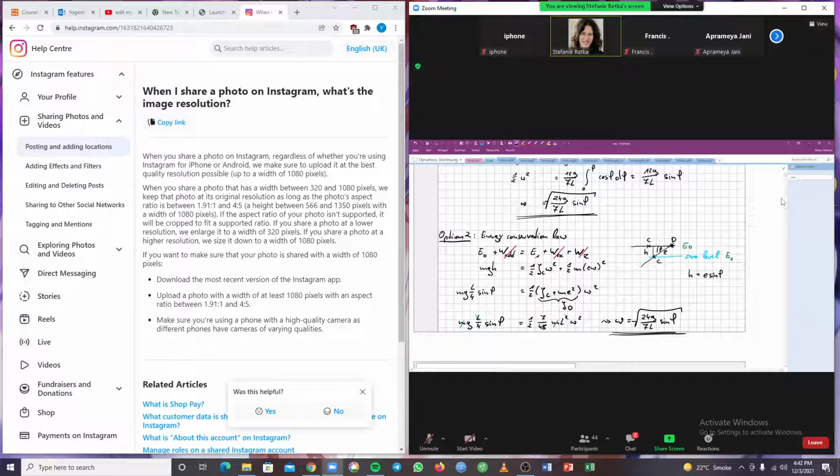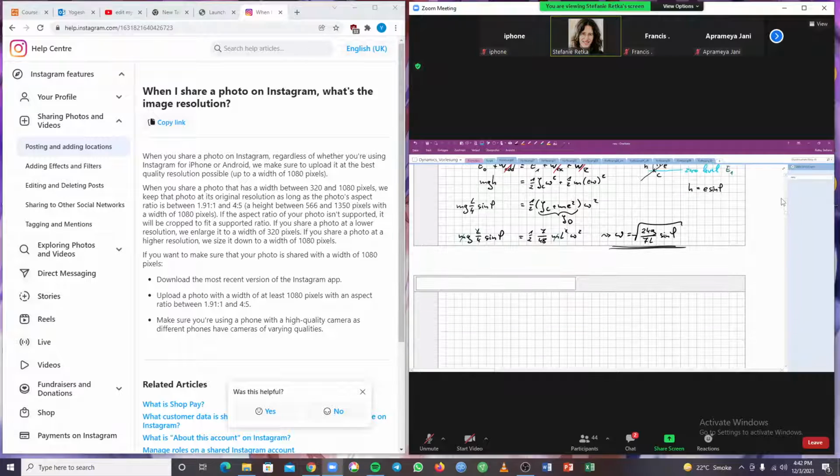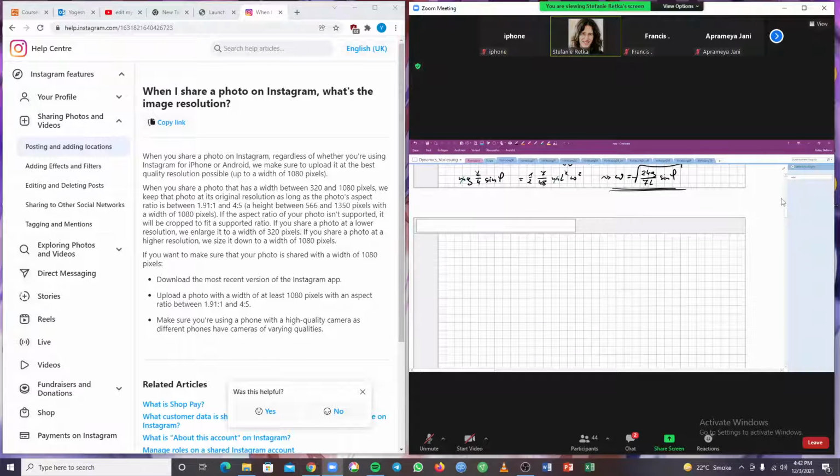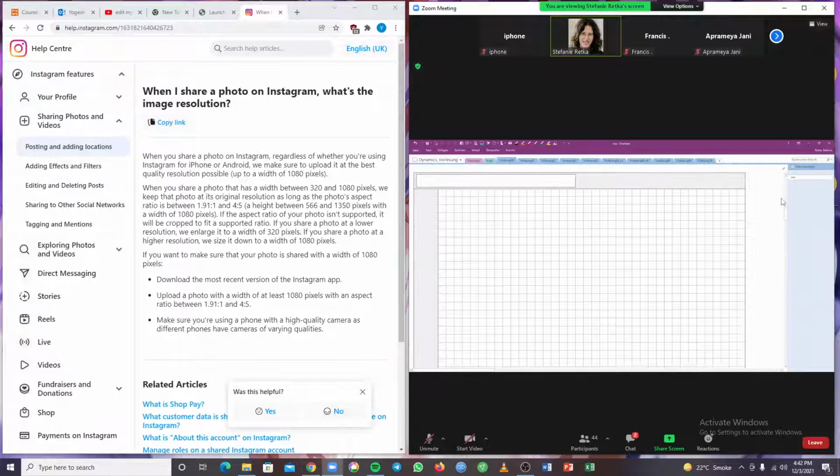Okay, so this is our second result. Now, we are also asked to find the velocity and acceleration of the center of gravity. Then we can use our standard equation, page 1 in the formulary for a circular motion. So we see the velocity of the center of gravity in case of a circular motion is radius times angular velocity. We just computed omega.